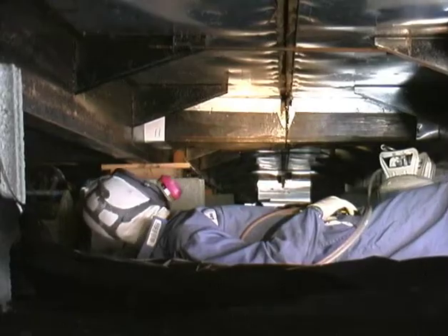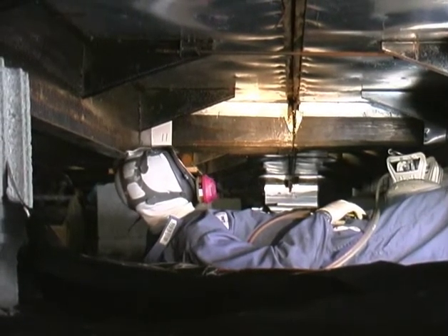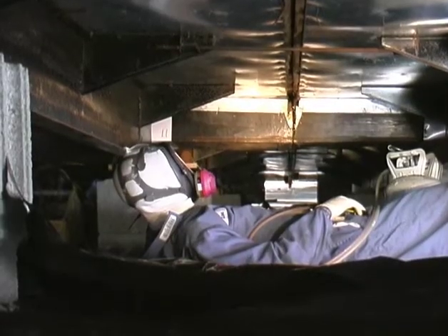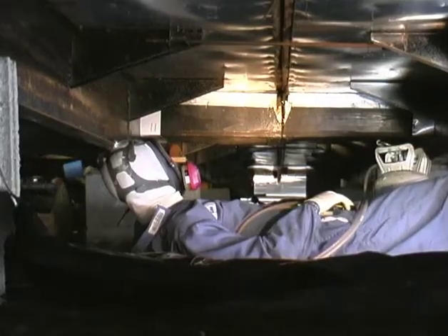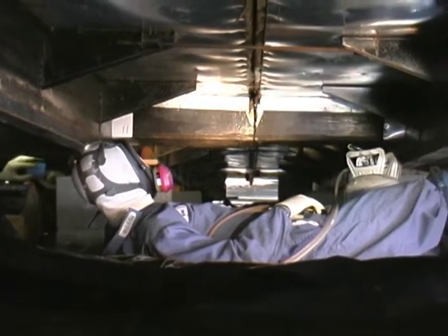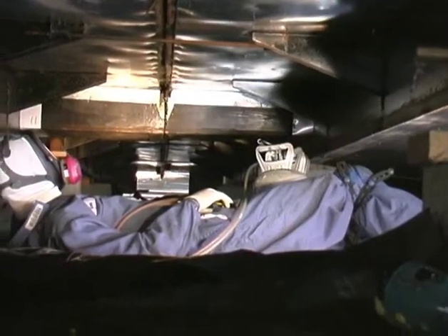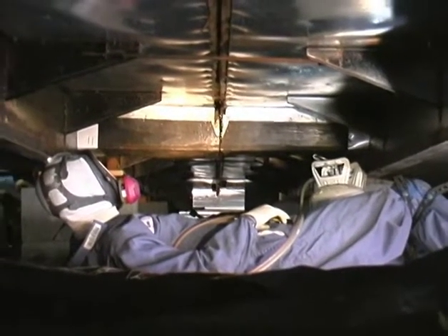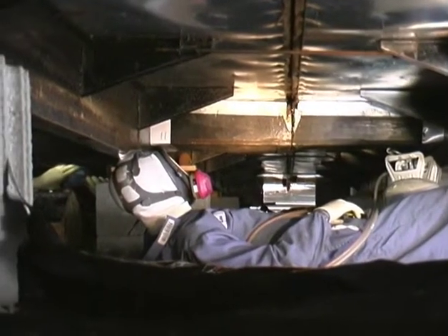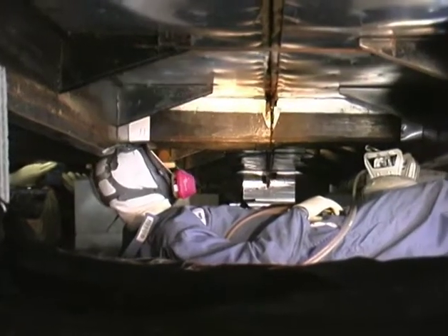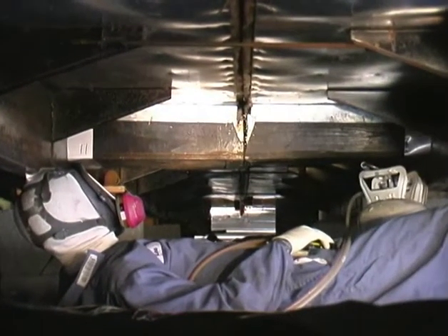Our installer Lee is going to go ahead and seal the crossover duct on this double wide mobile home with some 2-part foam. This is an atypical crossover duct. They're using some wood and metal for a duct. Typically what we see on a mobile home crossover duct is what's called a flex duct. It's sort of a flexible plastic that goes from underneath the furnace over to the other trunk line.